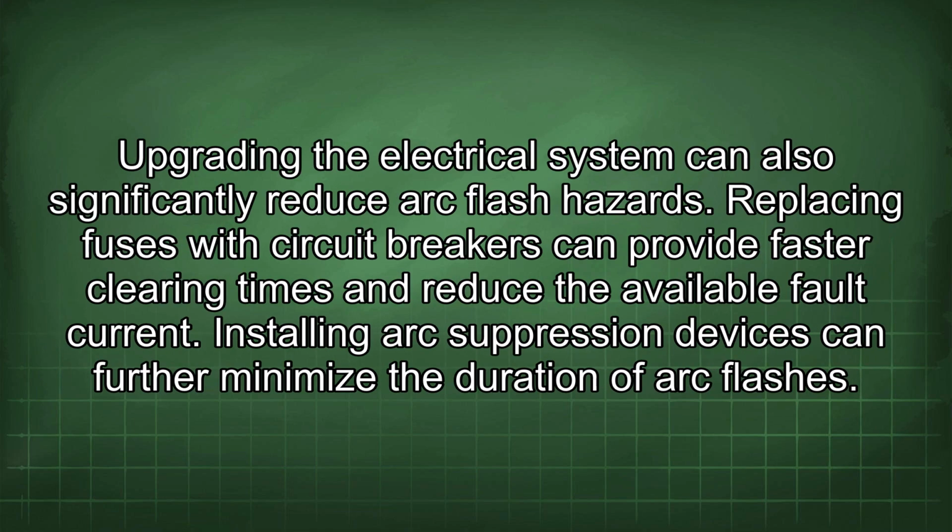Upgrading the electrical system can also significantly reduce arc flash hazards. Replacing fuses with circuit breakers can provide faster clearing times and reduce the available fault current. Installing arc suppression devices can further minimize the duration of arc flashes.